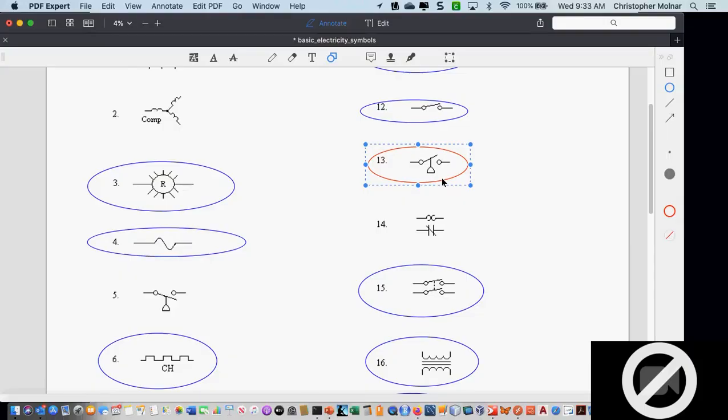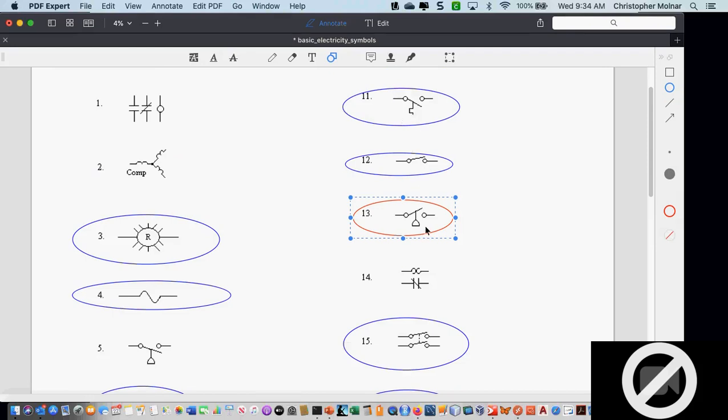We haven't defined it yet. What is it? Pressure switch. Okay, it's a pressure switch. Anytime you see the little device with the plunger on the bottom, it's a pressure switch. Okay, thermostat looks slightly different. See the difference on the 2? Okay, the little plunger.